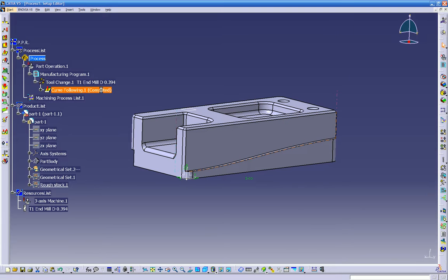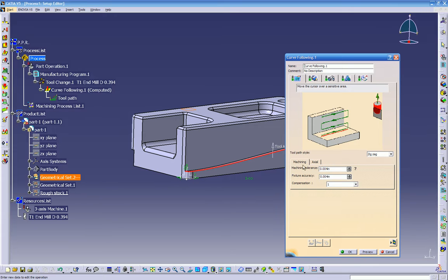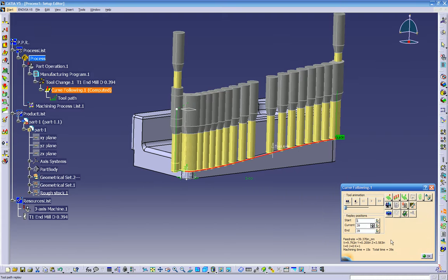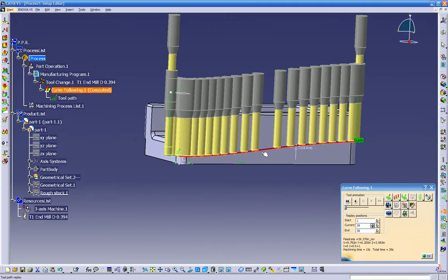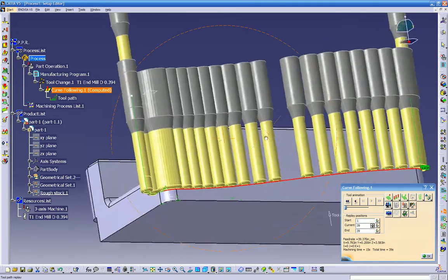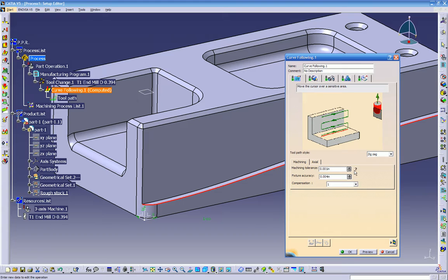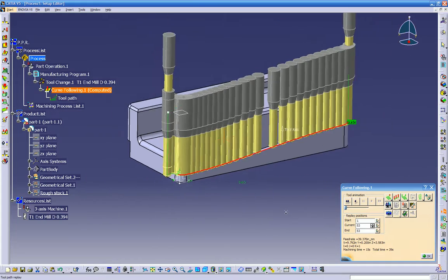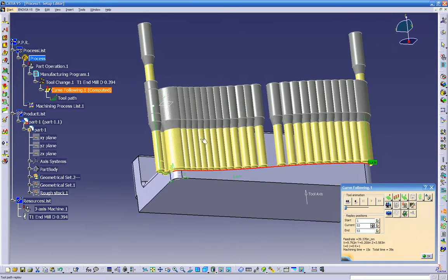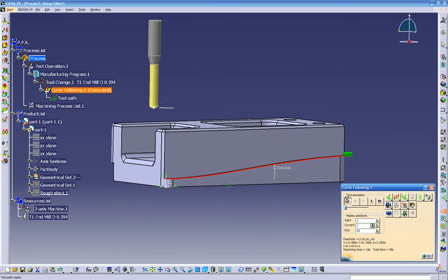And we go back into the operation, double click here. And over here on the tolerance, if we decrease this, let's change it to 1000. Look at the difference. See the tools, we get more tools. So our tolerance is better. So if you want to have a nice finish on the part, that's the place you come and change it. So it will show you right here. It's a tolerance. So the smaller you make it, the bigger the program gets, but the finish of the part is going to look so much better. So look at the difference, how many tools we have, all these positions.